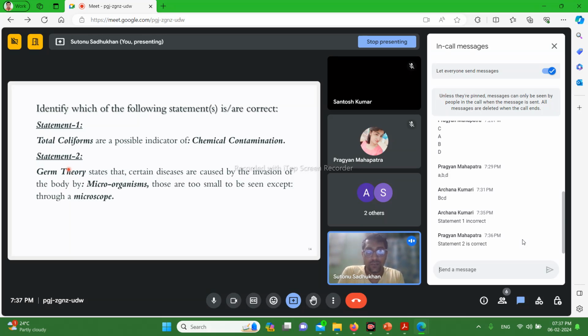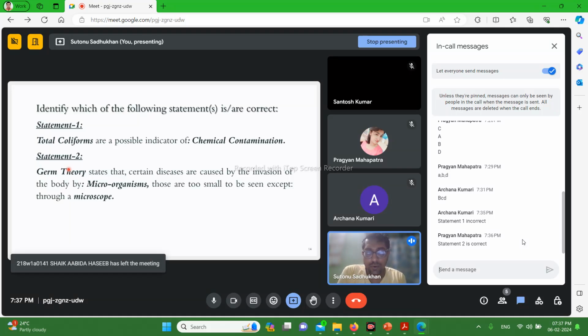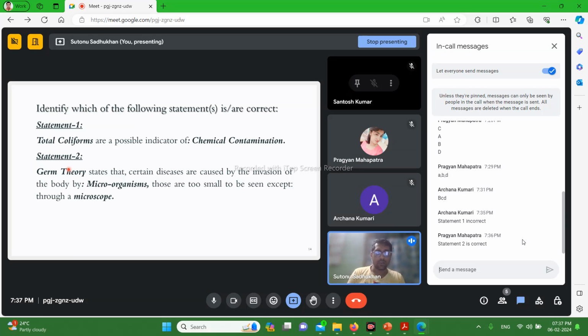So if the water is taken, the biotechnologist collects the sample water and they incubate that water, and they use certain medium like from gelidium, agar agar, these are what is called nurturing for the bacteria. And after certain time, if certain amounts of CFU or colony forming units of bacteria are visible, then they will say that yes, we can confidently say that there is indication of biological contamination in the water, right? But it is obviously not an indicator of chemical contamination.